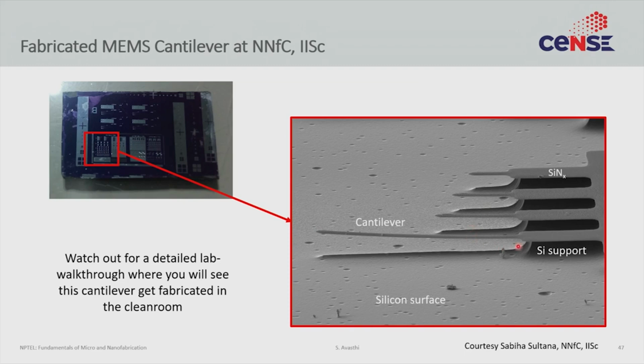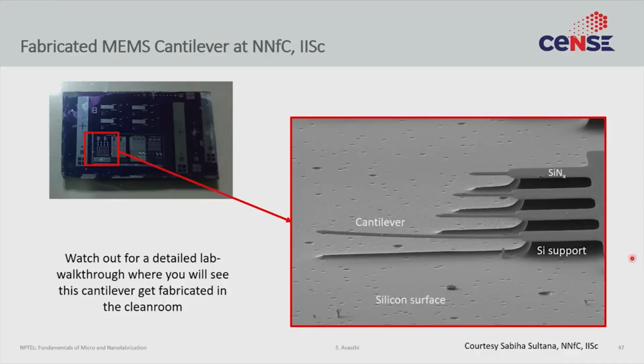You can actually tell that we do an isotropic etch by the shape of the etching that we are getting, remember? So we're getting this spherical or smoothish looking profile, not vertical ones, because we are doing an isotropic etch. But you also see evidence of the original anisotropic etch that we did. So again, if you look at the SEM from this side, you actually see relatively flat walls. So it's a combination of isotropic and anisotropic etch, and you can get the cantilever.